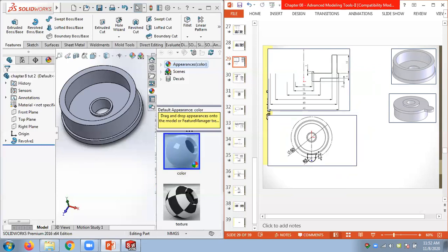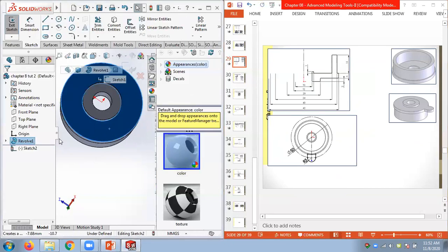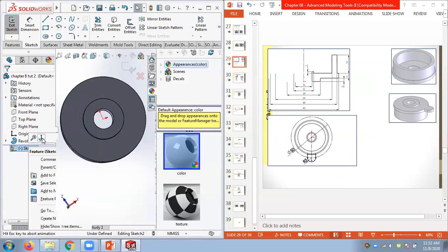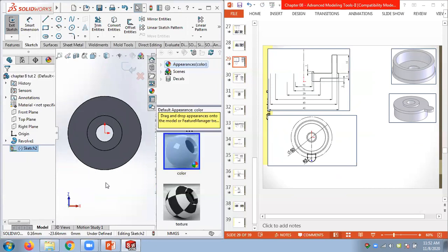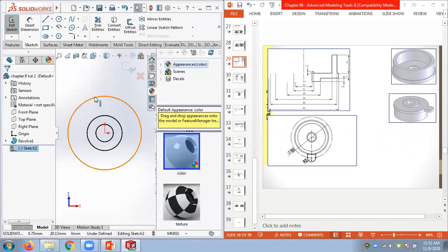The sketch is simple, you don't need to worry much. So we can take the bottom shape here, go to sketches, if you want to make it perpendicular like this. Then draw this shape. If you want, you can make hidden lines visible. And we have to draw all these center lines again to make it centered.